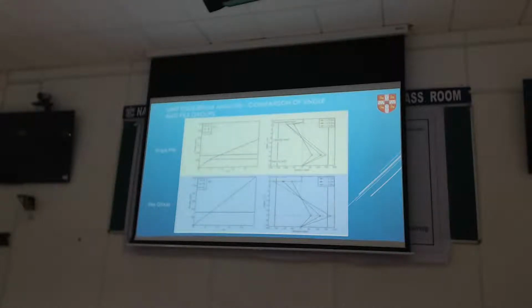Pile groups are slightly more tricky. First of all, this is almost a linear increase with deflection, which kind of makes sense. If you've got enough piles to make a frame, the more deflection I give, the more movement I get, and that's just a linear relationship.